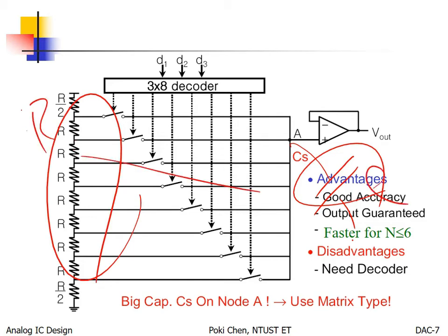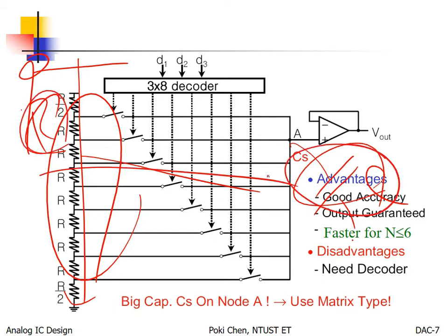You can see to reduce the power from here to there, you need to increase the resistance. However, by increasing the resistance, you will harm the charging or discharging speed of the parasitic capacitance. You cannot please everybody. You can only please R or C, but not both. Wow, that is some hard issue for you to make the decision.